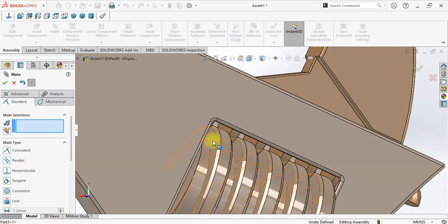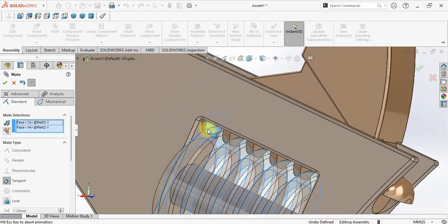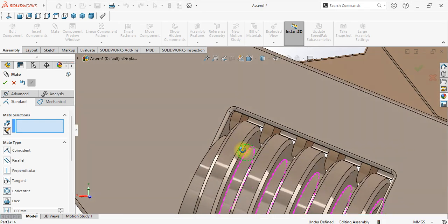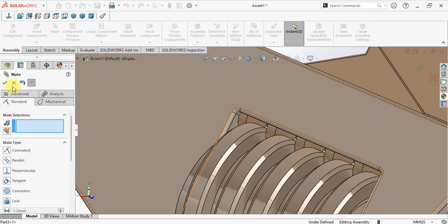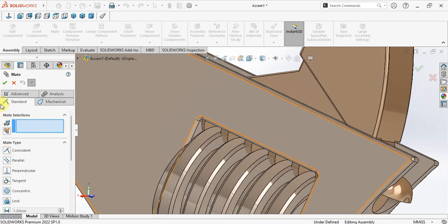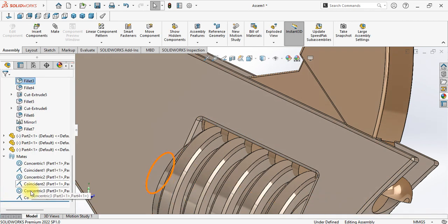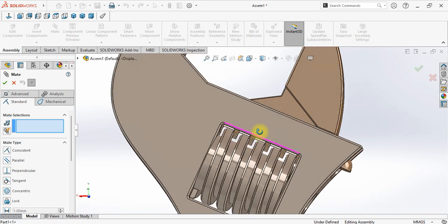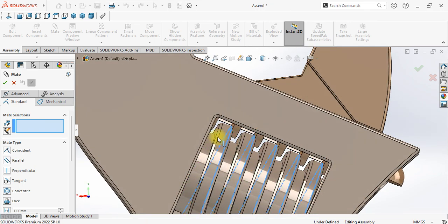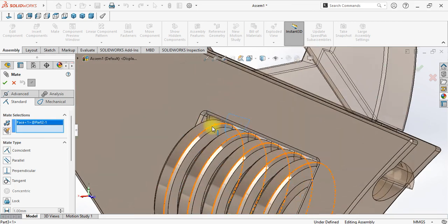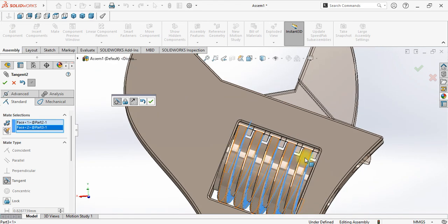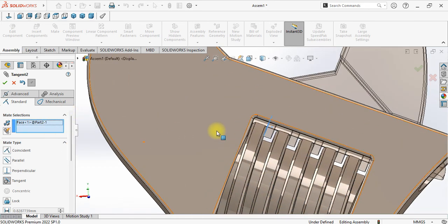on this face of this roller and this face. Okay, maybe we can try again. Maybe we can delete the mate first. Okay, we can try again. We can mate again. Select this face and this face. Something is wrong.